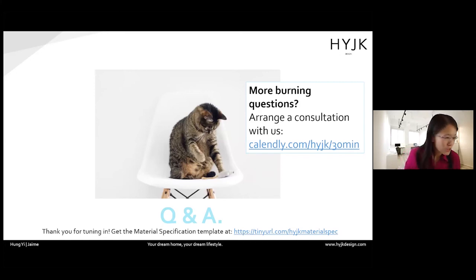Okay, so some recommend vinyl can be used in the kitchen, but some don't. Share with us your thoughts. Okay, vinyl can be used in the kitchen with no issue, unless you're looking to pour water to wash your kitchen, which I would suggest not to do. If it's going to be very, very wet, like a bath area, or an area where you're just really going to use a pail of water and pour water, I would say no.